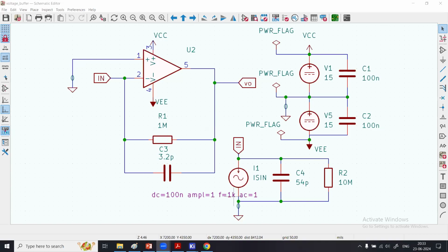Hello, so welcome again. As you can see, we have got an interesting circuit which is designed in real world electronics to develop some industrial applications. So, what you see on the screen, there is an operational amplifier. Positive input of it is connected to the ground, and to the negative pin, we have got input signal applied. Pin number 5 here is the output.